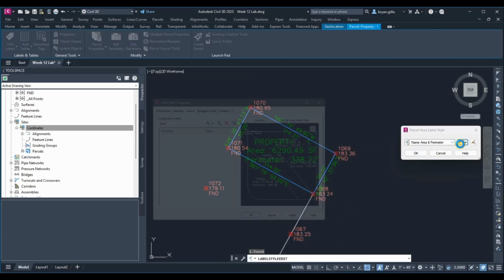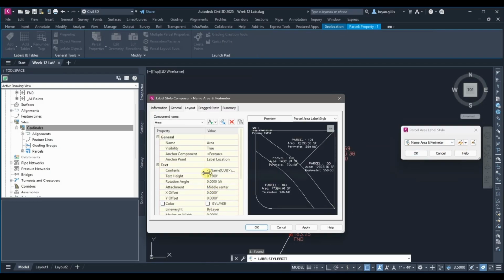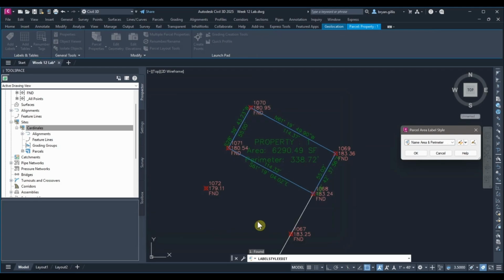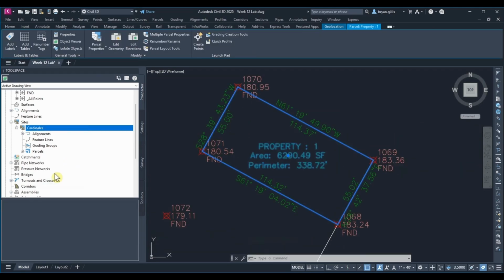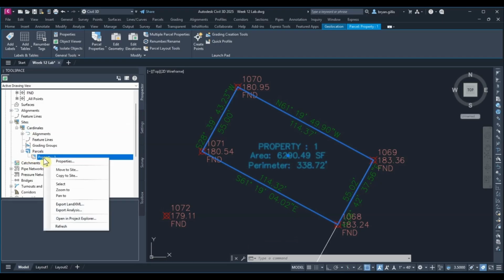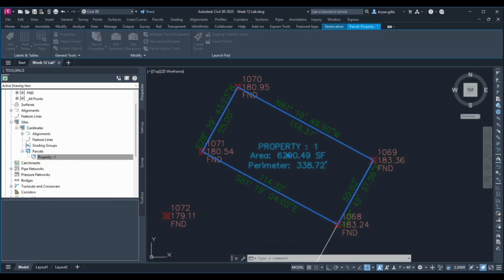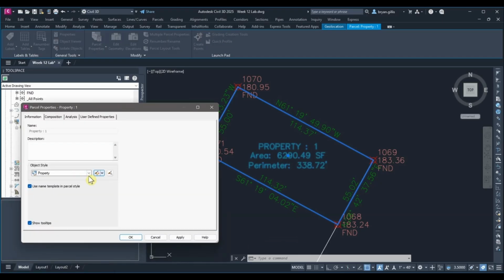I'm going to edit it, and then under Text, under the Layout portion, I'm going to change it from 0.15 inches to 0.1 inches. Now, you'll change heights several times as we go through the project, just for the sake of visibility and clarity. But that's all I'm going to do for right now. Just change it to 0.1.